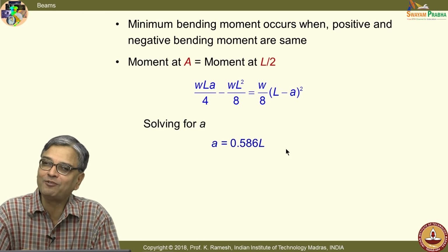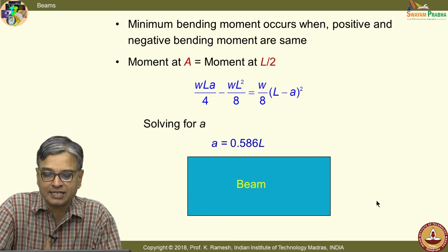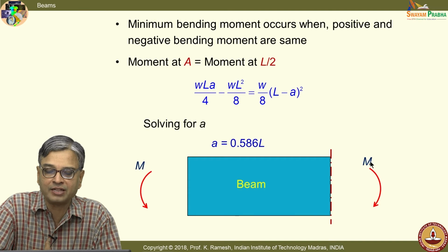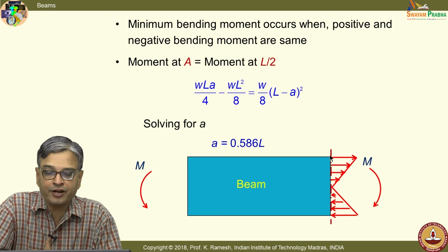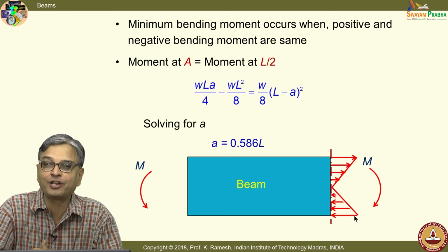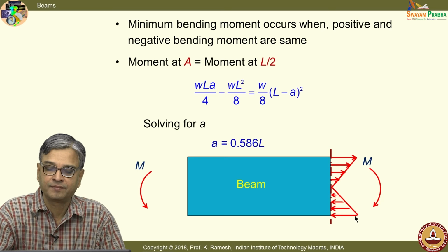But what you will have to appreciate is, when I have a beam, suppose the bending moment is in one direction, I am having this as clockwise bending moment, and when I see the resistance offered by the beam, it is tensile on the top and compression at the bottom, and mind you, the maximum tensile magnitude and maximum compression magnitude are identical, fine.